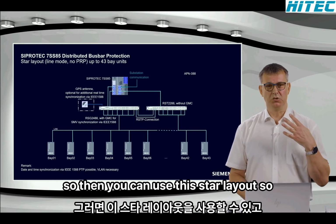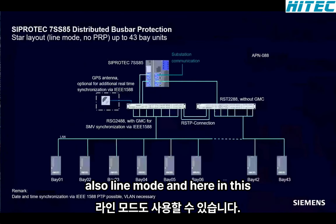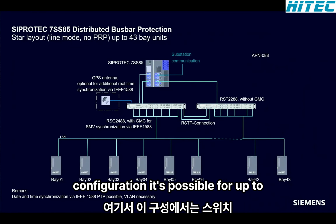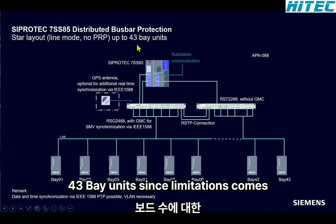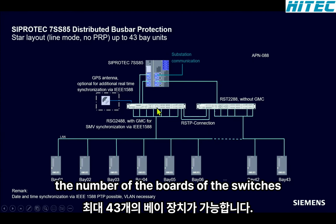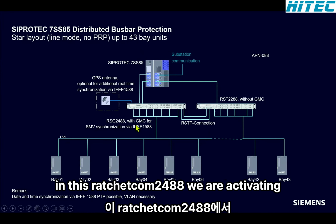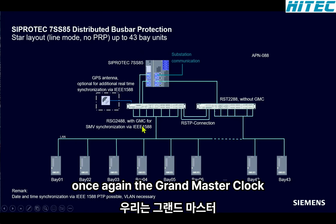So then you can use the star layout, so the line mode. And in this configuration, it's possible for up to 43 bay units. This limitation comes from the special limitation of the number of the boards of the switches. We use one RuggedCom RSG2488. In this RuggedCom RSG2488, we are activating once again the grandmaster clock.